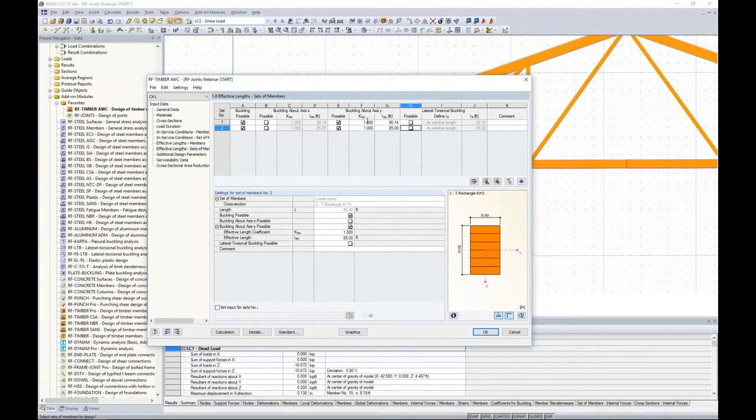Buckling about the y-axis or the strong axis, I am still concerned with this, but right now it is set to the full member length, the full set of member length. So it's pretty large, 90 feet and 85 feet. Maybe for uplift wind purposes, I have much smaller unbraced lengths here. For example, the upper might be 3 feet and then the lower might be 3.5 feet. So as a design engineer, you always want to pay careful attention to your unbraced lengths because this significantly affects our stability design.